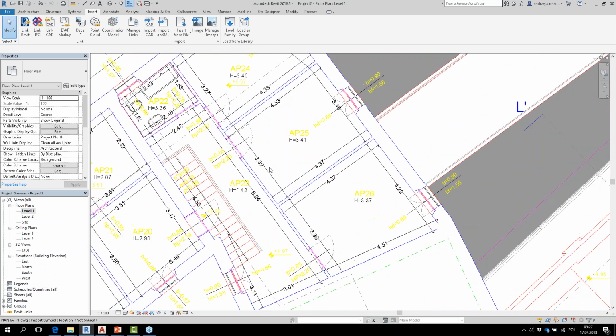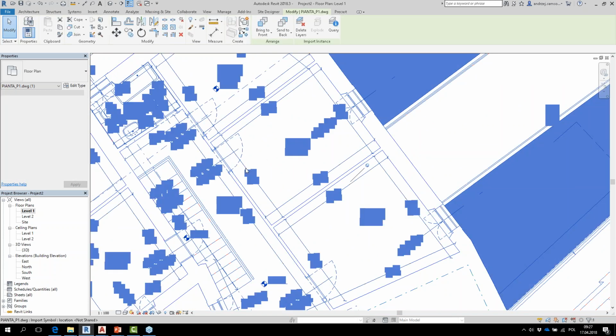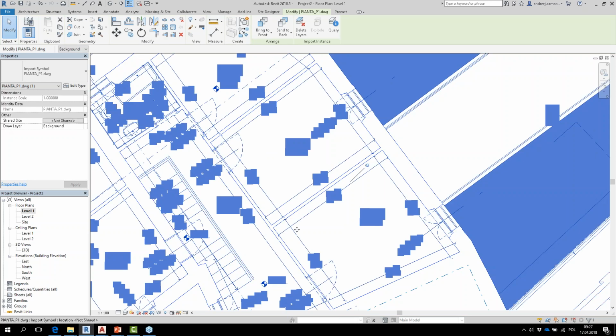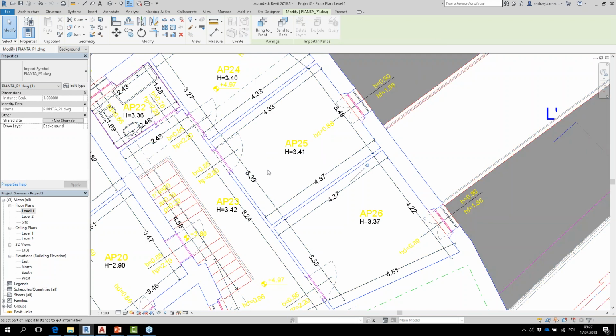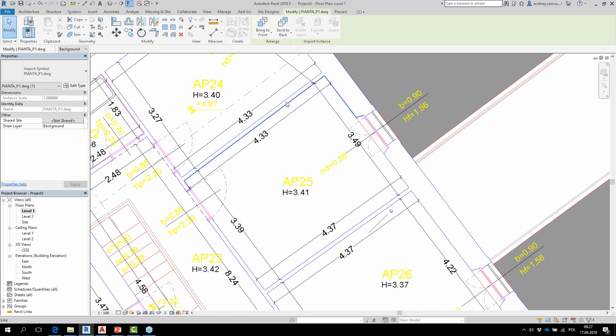Of course, I can also say that I don't need all the layers, and I can turn these layers off and on while working with it. So for example, I'm going to click on my DWG, and I have this icon on the top called query. I'm going to hit query, and look, it's already snapping to these elements, which are completely different lines and layers, right?